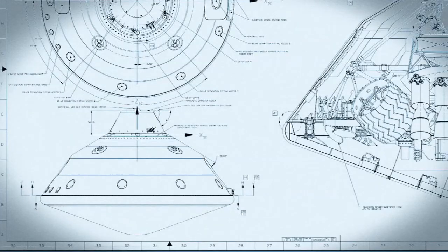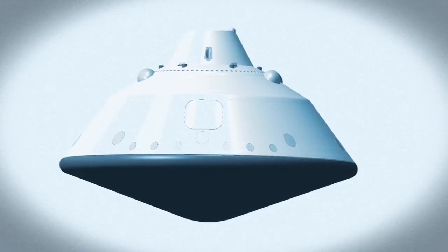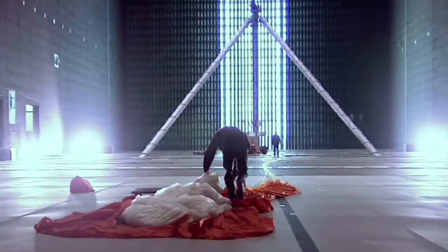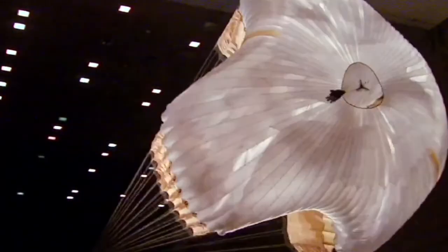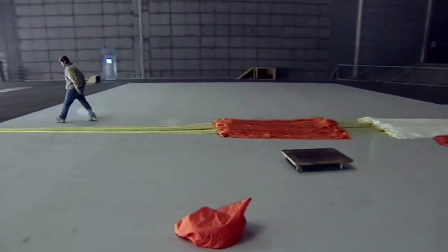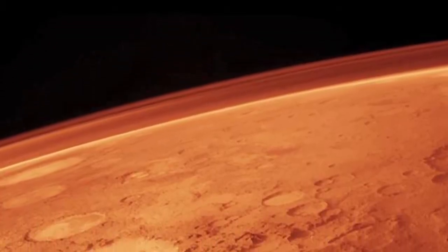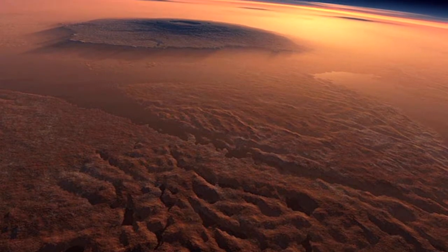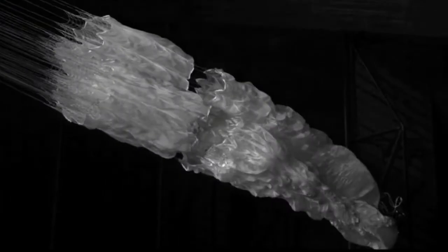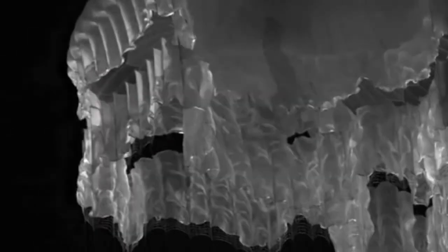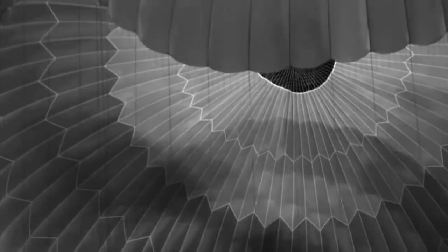The terminal velocity of the rover depends on the mass of the rover itself and its heat shield, and several different variables related to the parachute design: the material of the canopy, the diameter of the hemispherical parachute canopy, the number of suspension lines, etc. For simplicity, let's suppose that all parachute parameters other than the diameter of the canopy have already been determined. Our goal is to find the canopy diameter that is as small as possible but will correspond to the desired terminal velocity of 90 meters per second.